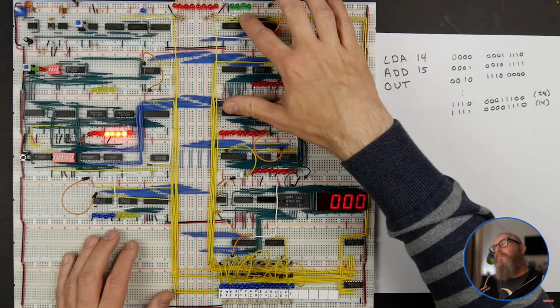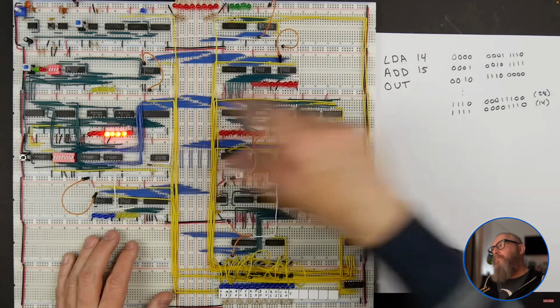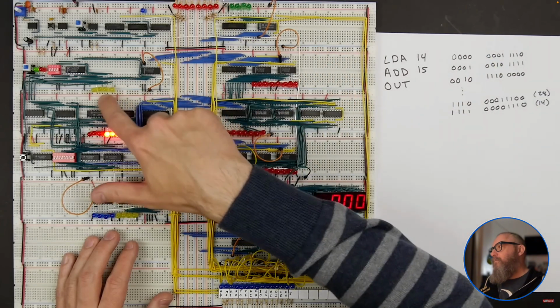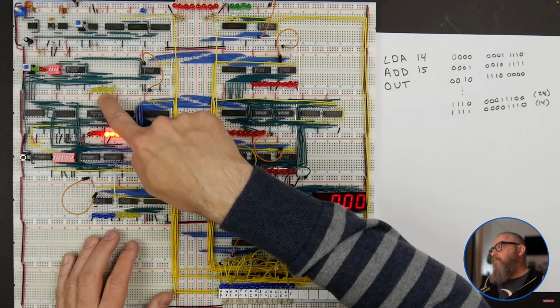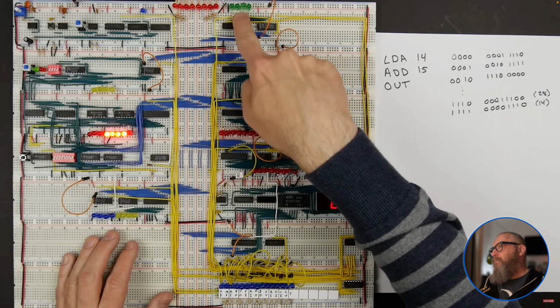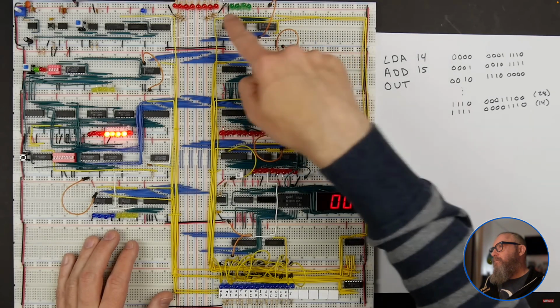So our program counter is at 0, which is where we want to start. And the first instruction that we want to fetch from memory is in memory location 0. But in order to get to memory location 0, of course, we're already there, but we're just sort of there by accident. Really, to get there, we need to take the contents of the program counter, which is 0 in this case, but as we get to the next instruction, you'll see it's 1 or 2.